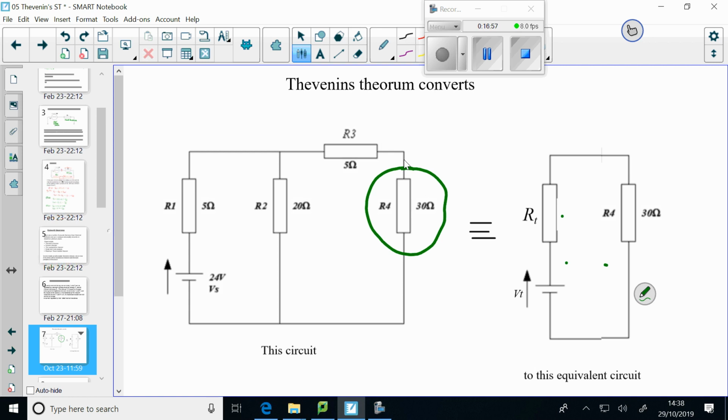Because if we take that resistor in isolation, it's these 4 components that are applying voltage to it. So the voltage this resistor sees is just what was dropped across it. So there's the simplification. If you want to know how that circuit would work with 10 ohm, 20 ohm, 30 ohm and 50 ohm resistors connected to it, you can do the complex calculations once, turn that circuit into this one, and then it's quite easy to do a voltage divider and find the current or the voltage to the load using the equivalent circuit a number of times over. An example will better show how that works.